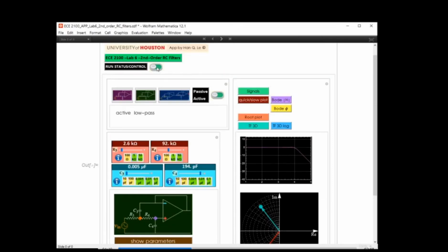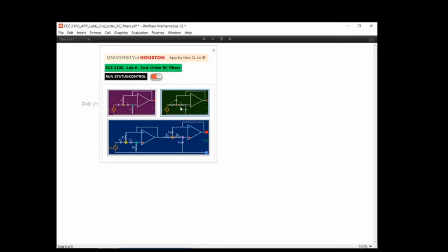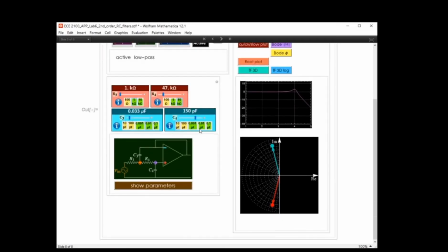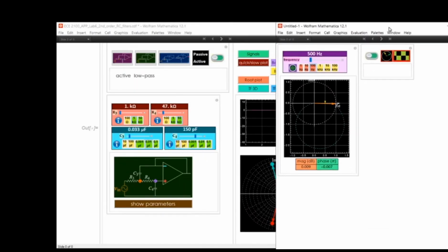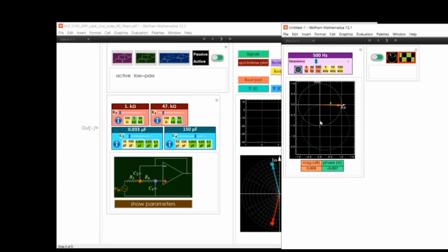The app is turned off and on again in order to restart with the original default design. Once the circuit has been built and is ready for testing, click on Signal button. A pop-up window shows the Nyquist 2D plot, which allows one to get a gut feeling where on the frequency scale to look for the resonance and the rapid phase change behavior. Since the frequency control is on the linear scale, it is much more sensitive to locate the resonance peak than the log-log Bode plot.